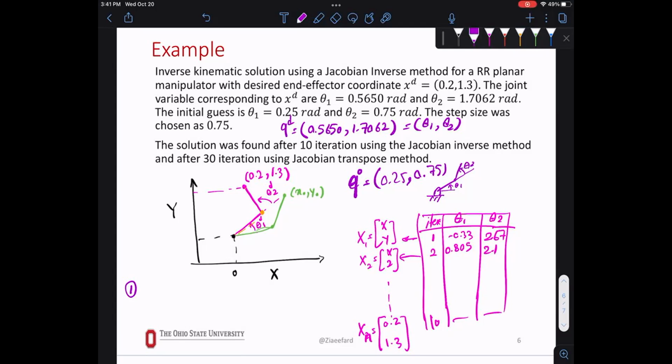Sometimes you might not converge. There's no solution. Sometimes you didn't think about the reach, like whether it's reachable, right? So your algorithm is trying to work and never finds anything. And since you don't have anything to exit out of, it just runs forever, right? So you have to think first, is it reachable. Second, make sure that there's righty or lefty. And then third, you just run the algorithm, and you'll have a good threshold for convergence.